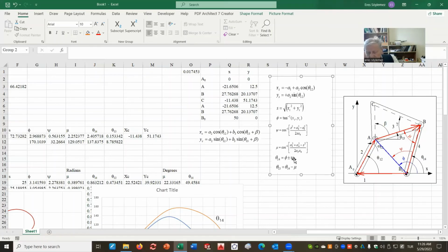And another thing is conversion of Cartesian to polar coordinates. This formula we use quite often. Thank God we have an A tan2 function available in Excel, but there is no function that will give me the magnitude of a vector whose x and y components I know. Or there's no formula that will give me the angle or magnitude using the cosine theorem.